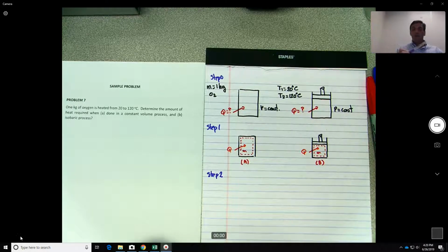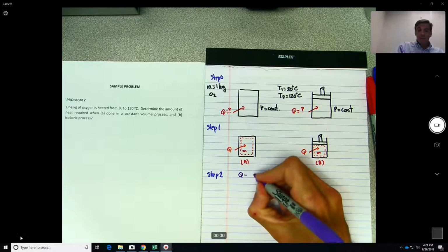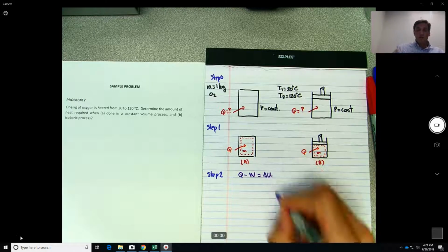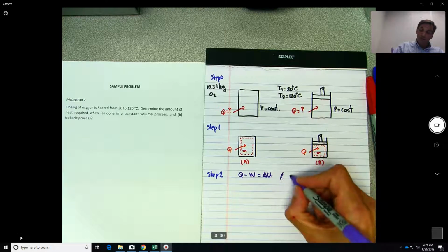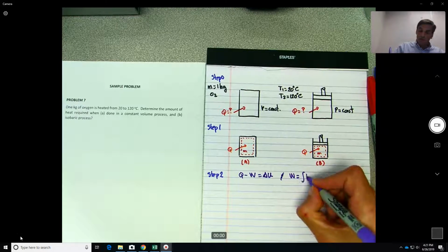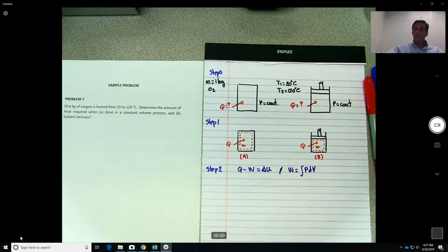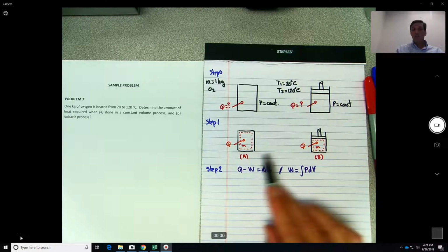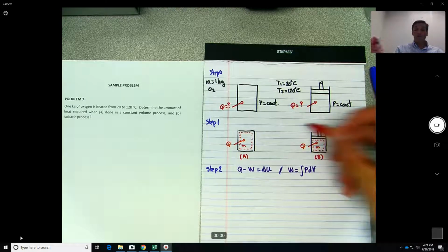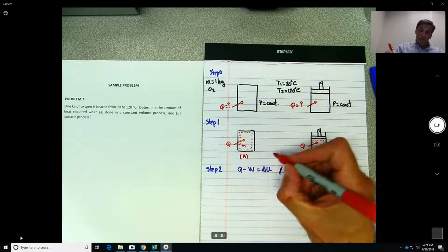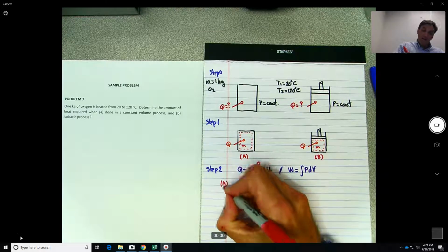So you know, for the first principle of thermodynamics we have 2 sign conventions. Let's use this one over here. Q minus work equals the change in energy, and under this definition the work is equal to P dV. Okay, so let's just first solve the problem using the specific heats. So if you look at the figures over here, is there any work done? You cannot see really any W shown anywhere. So this is 0.